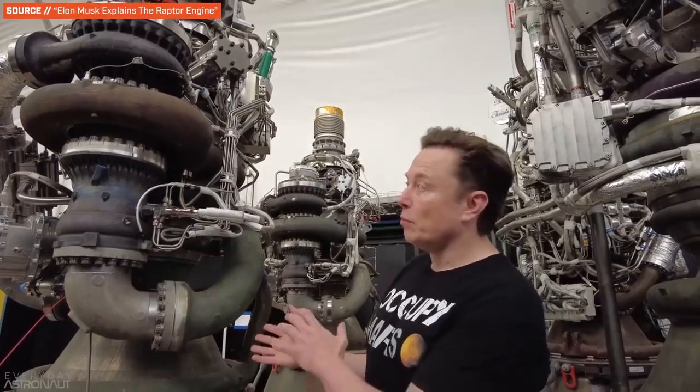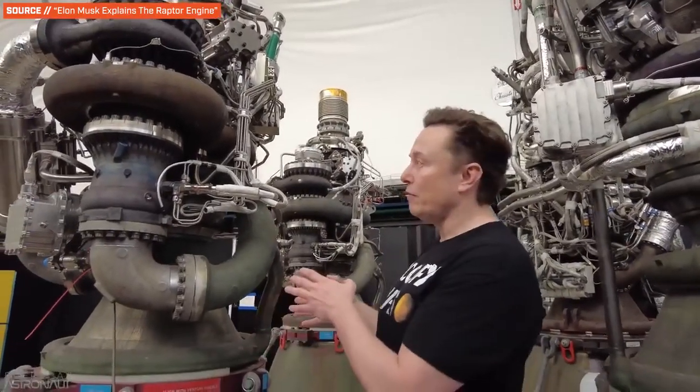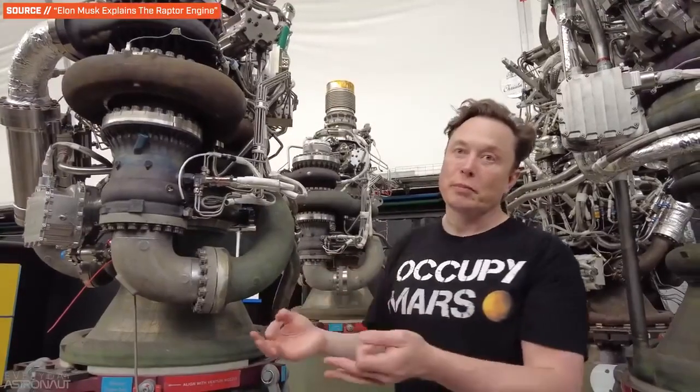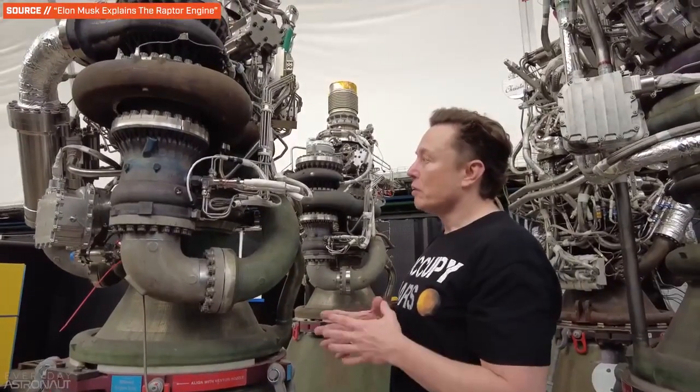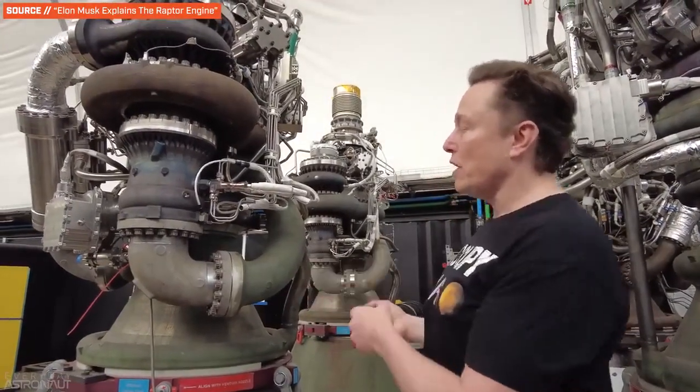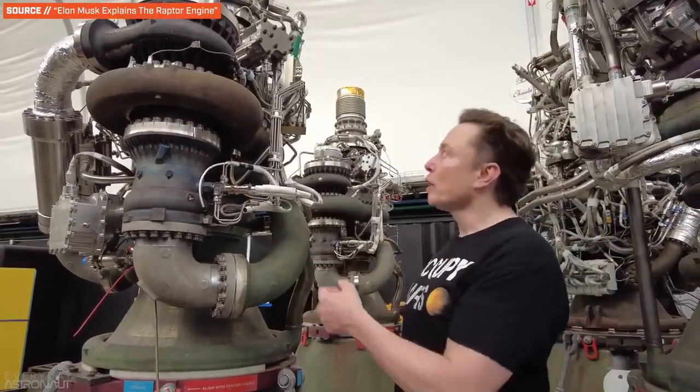So you can either have more main chamber pressure, or you can have the pumps put less stress on the pumps. Although, looking at SpaceX's Raptor engine, they like to push it all as much as possible for the ultimate performance. But as attractive as the positive attributes of full flow are to engineers, it's often considered not worth it because of its extreme complexity.